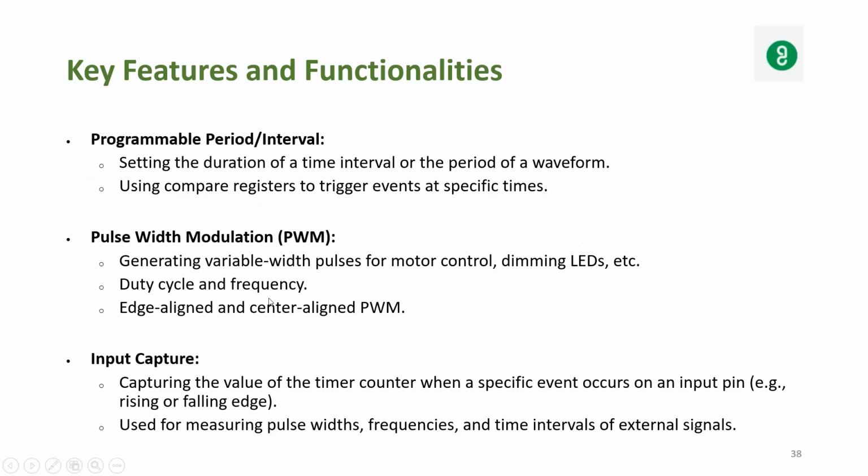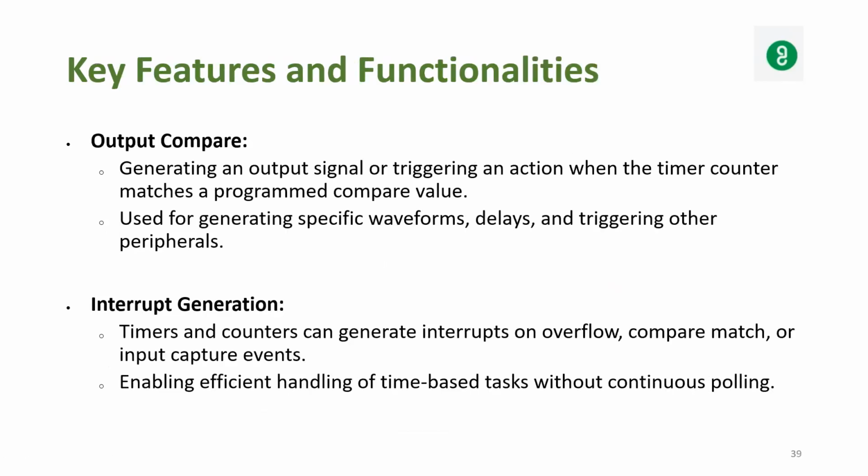Input capture. It works like this: whenever a specific event occurs at the input, it captures the value of the timer count. So it is used for measuring pulse width, frequencies, and time intervals of external signals.